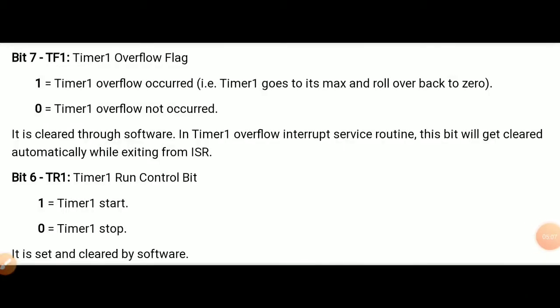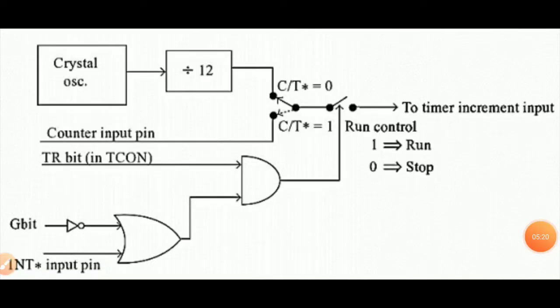Bit 6 and bit 7 are the similar flags, the run flag and the timer overflow flag for the timer 1. Now this diagram explains the control process of the timers and counters, and this is called the logic diagram of timer controls, timer counters.